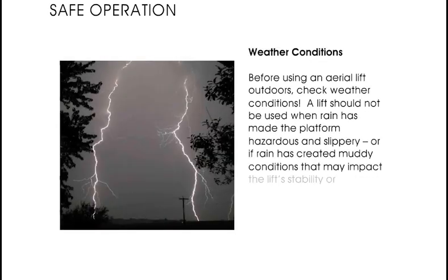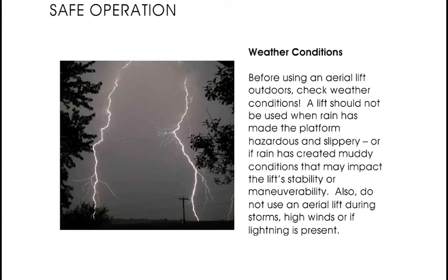Before using an aerial lift outdoors, check weather conditions. A lift should not be used when rain has made the platform hazardous and slippery, or if rain has created muddy conditions that may impact the lift's stability or maneuverability. Also, do not use an aerial lift during storms, high winds, or if lightning is present.